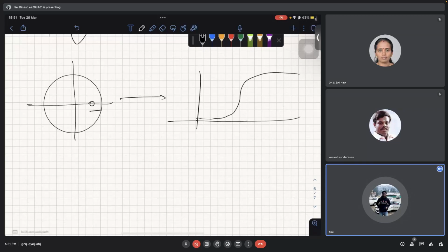But as r tends to 1, the valley becomes sharper, is it? And then we have also seen that if we want a low pass filter, we can also put a pole at the pass band side, so that whenever there is a pole, there is a gain in the magnitude response, and whenever there is a zero, there is an attenuation in the magnitude response.